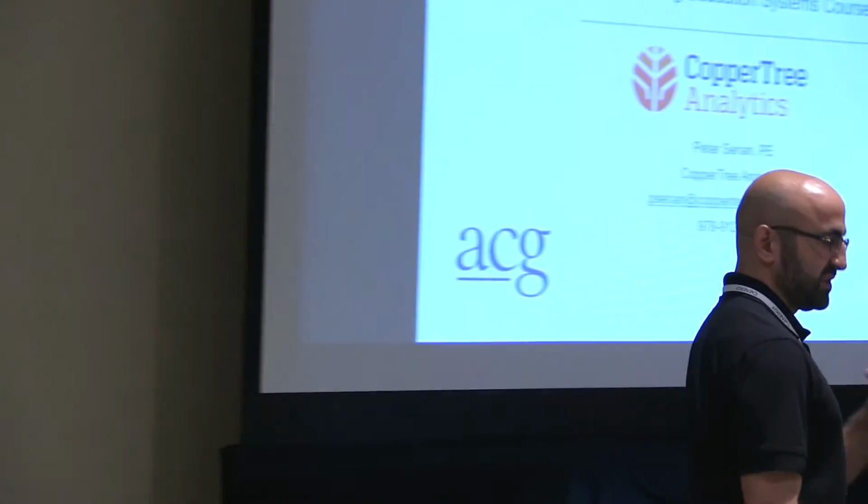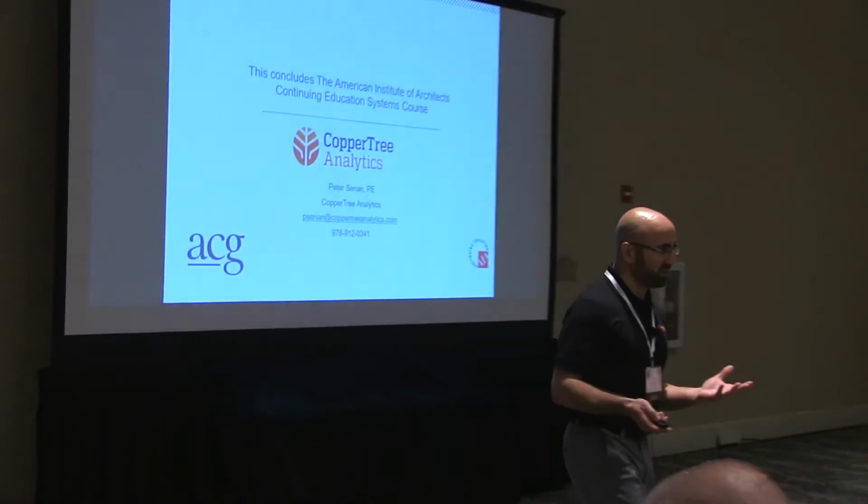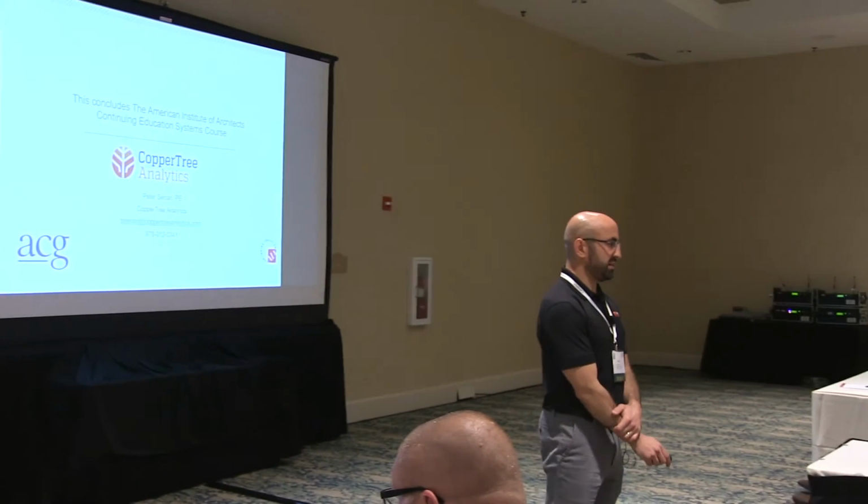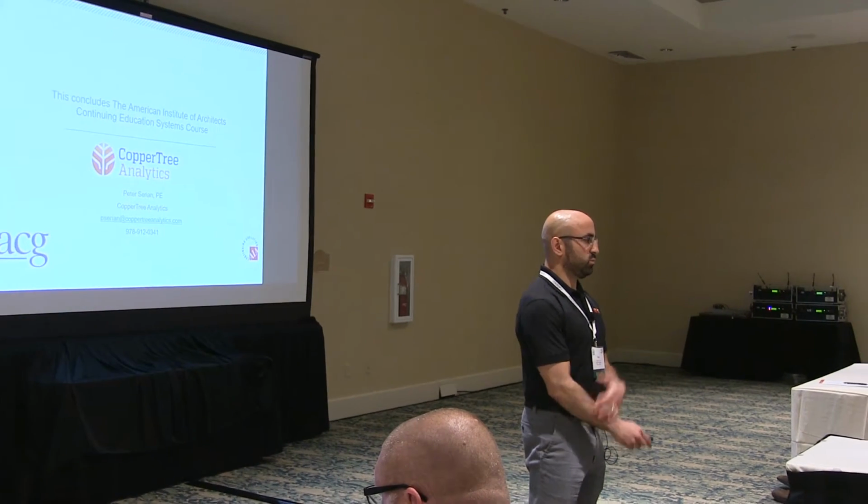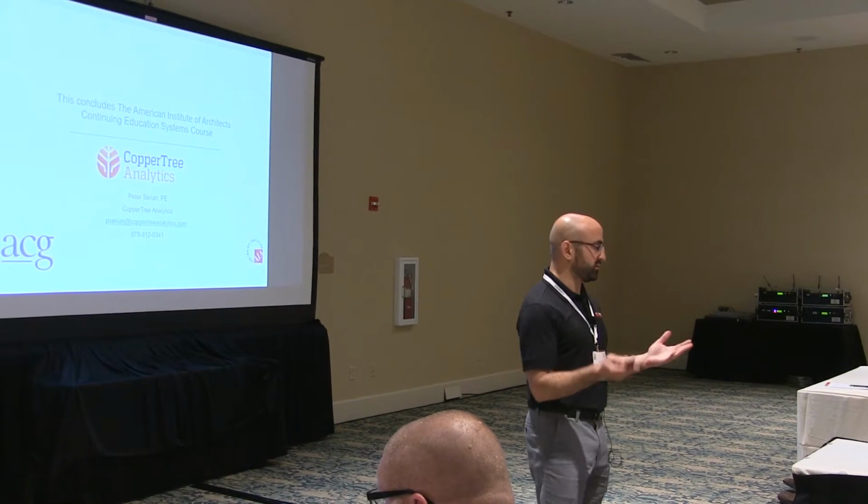Yes, that's a good question. So sometimes you have packaged equipment or building systems where those points may not be getting pulled into the front end, which is what a lot of these edge devices are relying on, that central warehouse of data. So in that case, the way we would do it is we would actually deploy our edge device on the specific controller of that piece of equipment, whether it's a chiller plant, and we could talk LonWorks and Modbus and those protocols.